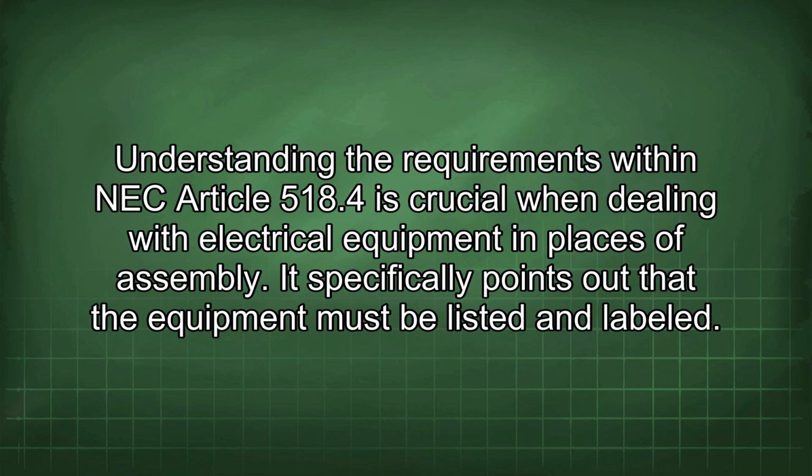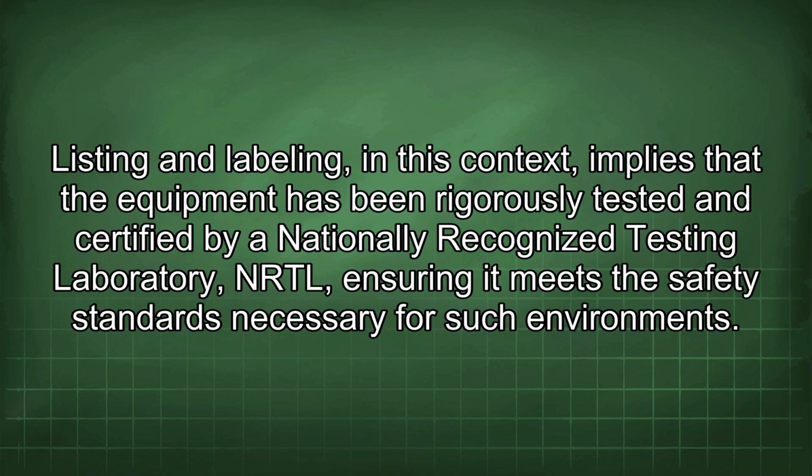Understanding the requirements within NEC Article 518.4 is crucial when dealing with electrical equipment in places of assembly. It specifically points out that the equipment must be listed and labeled. Listing and labeling, in this context, implies that the equipment has been rigorously tested and certified by a nationally recognized testing laboratory, NRTL, ensuring it meets the safety standards necessary for such environments.